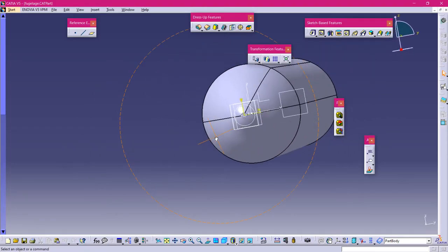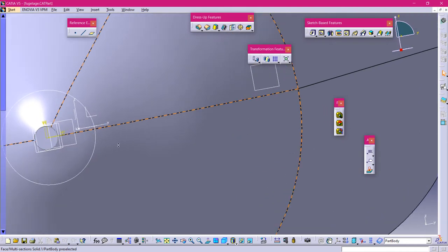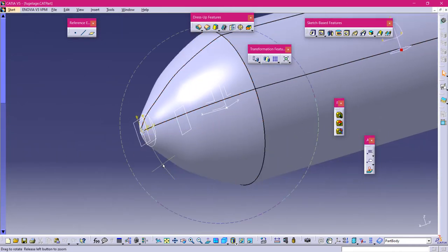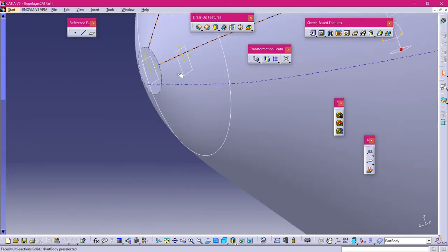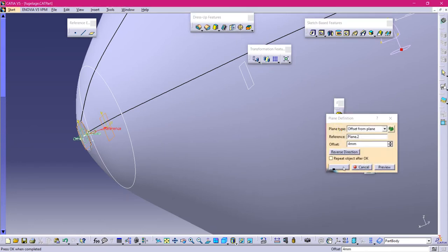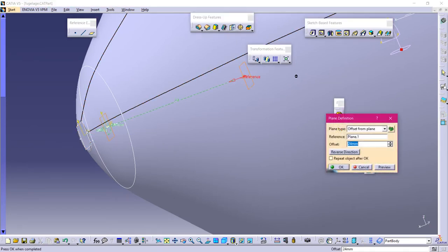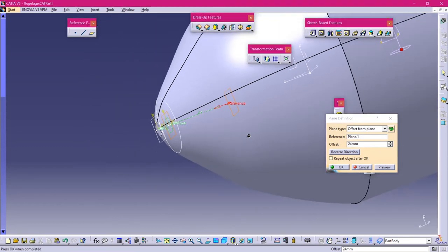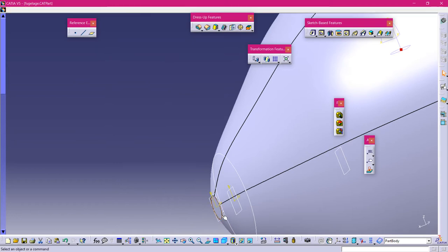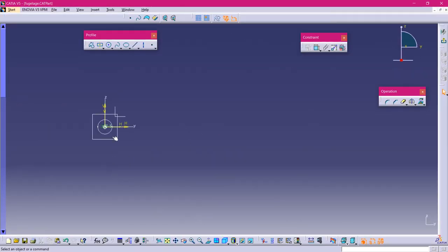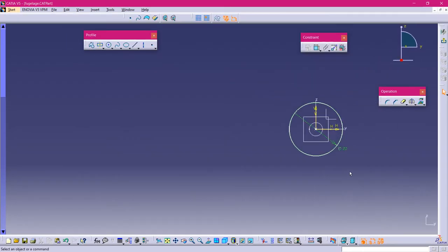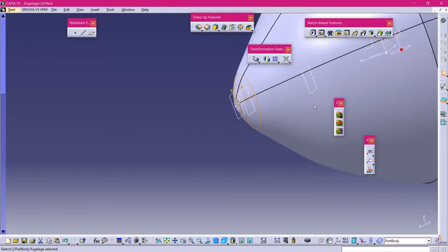Okay guys, I have just designed our aeroplane using multi-section. So I have made little modifications. Select two planes very near to each other. See these two, these are just 4 mm apart, and then these two planes are 24 mm apart. You can see here. So I had sketched here, sketch the front portion. That's 5 mm diameter, and the next section was 20 mm diameter.